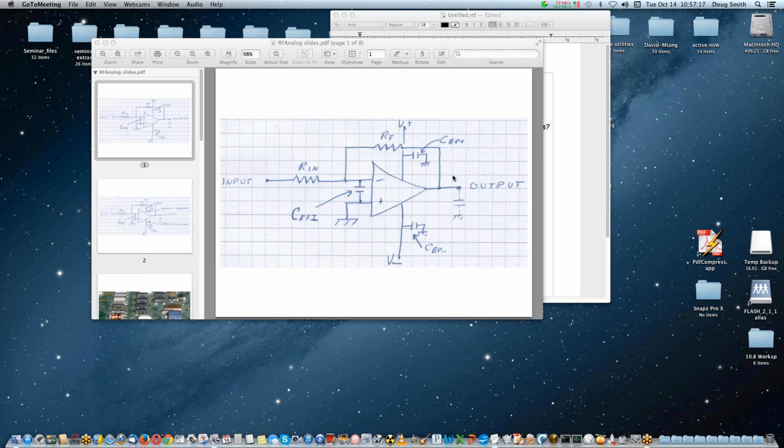A lot of products have plastic boxes today, and you might just put your cell phone right on top of the thing. You can simulate that with a cell phone-like antenna, like a little coaxial dipole, fed with 600 milliwatts at 1850 MHz or so, and each side of the dipole would be exactly 3 centimeters for that frequency. So you have a 6 centimeter little dipole. And you can figure that you can get that effect.